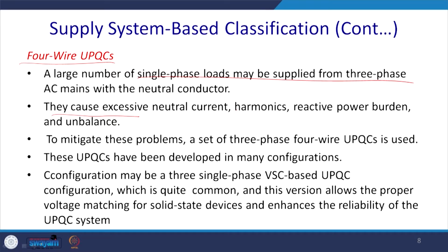Harmonics may be a source of harmonic reactive power burden as well as unbalanced current. If there is an unbalance due to the voltage, it is very difficult to clean up by this shunt path. We assume that it is not there, DVR already compensated. But anyway, since DVR is an integral part of this system in the case of the UPQC, it has been cleared up.